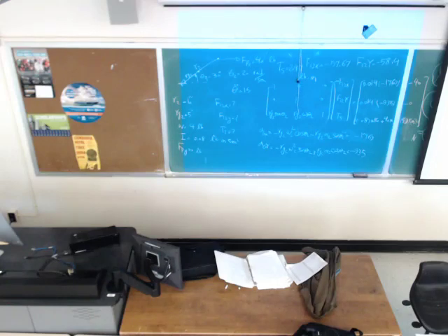I would like to talk about a term that you might see in the book or in the homework: shaking force. The force applied to link 2 coming from the ground is F12x and F12y. If I ask you what the magnitude of the force coming from link 1 to 2 is, we can say F12x squared plus F12y squared, under a square root. It gives you the magnitude of the force, and we call this shaking force.